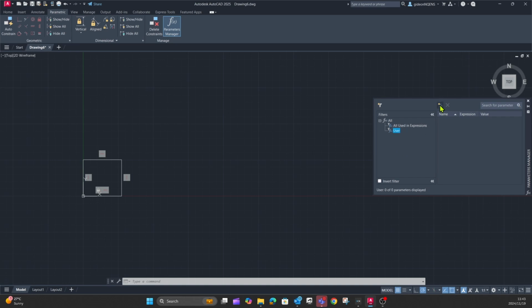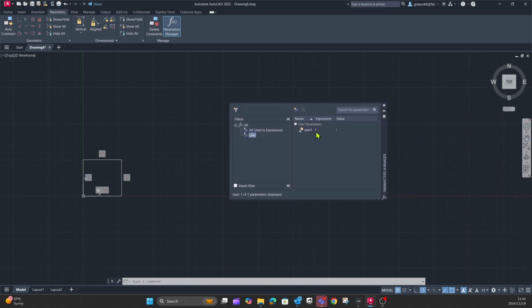Going to keep it simple, so here we do have the option to create our parameters. Just moving this table a little bit in, so here I can right click and just delete that because I actually want to create specific parameters. Now this user parameter, I can give it a name. I'm going to create one called height. The expression, I'm going to utilize a dimensional value,